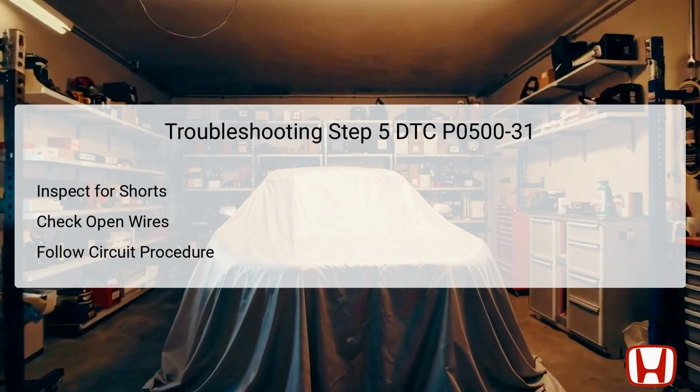Use diagnostic tools to determine if the VEL PWM signal wire is shorted to ground, which can affect the overall performance of the TCM. Should you discover any anomalies during this inspection, you have identified another potential cause for the DTC. If shorted or open wires are found, they must be repaired or replaced, thus allowing for the proper signal to transmit from the sensor to the TCM, leading to the accurate operation of the transmission system.